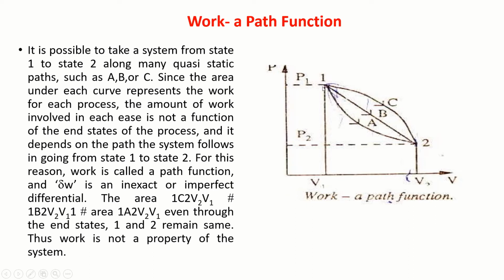The same way, the system is undergoing change of state from state 1 to state 2, maybe by following this path. Other than pressure and volume, some other property may also be changing. These values are changing. Since I have drawn this on a pressure and volume coordinate system, the unit of pressure is Newton per meter square, pascals. Unit of volume is meter cube. If I multiply these two units, I'll get Newton meter, which is nothing but the unit of work.